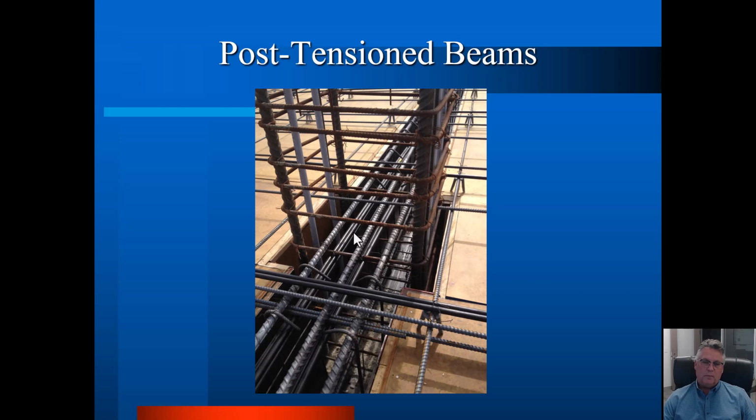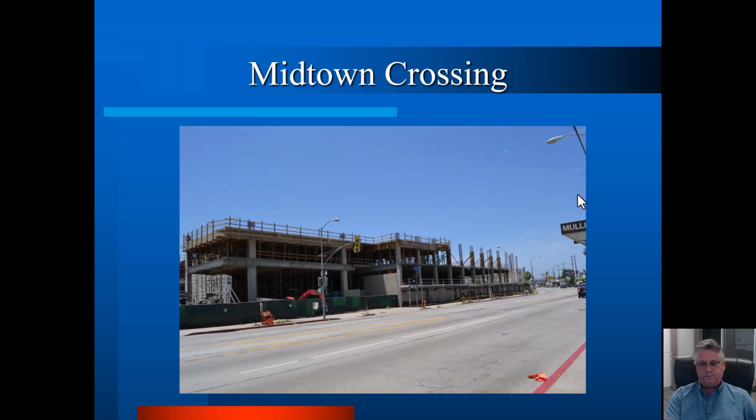There's no strain compatibility. All the things you learned in reinforced concrete kind of go out the window. The pre-stressing is doing its own thing, and the concrete's doing its own thing. And that's, I wouldn't say a complication, that's something that makes it very interesting in analyzing and understanding post-tension concrete. Notice we will also always have bonded reinforcement wherever we have unbonded reinforcement. The two will always go together.